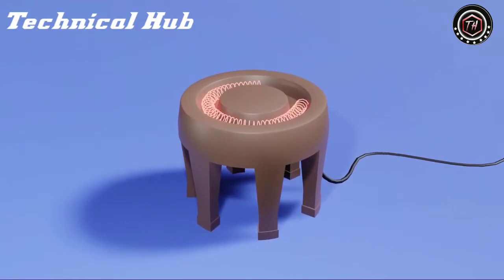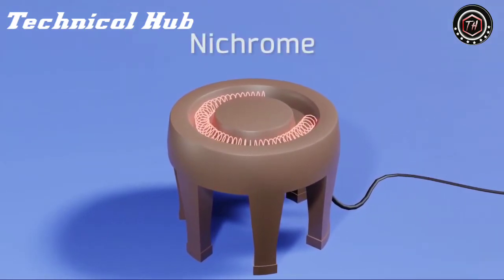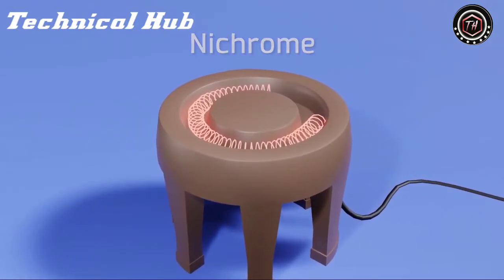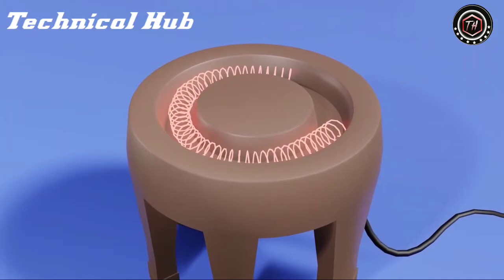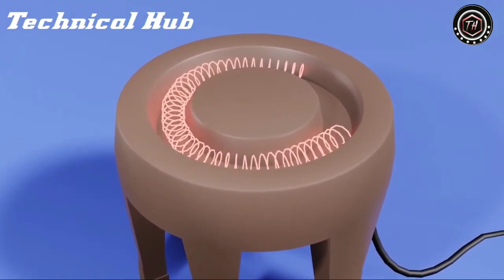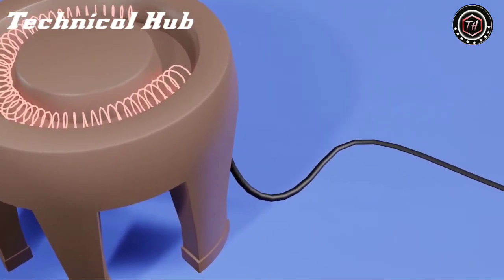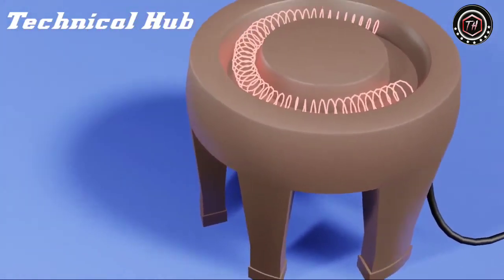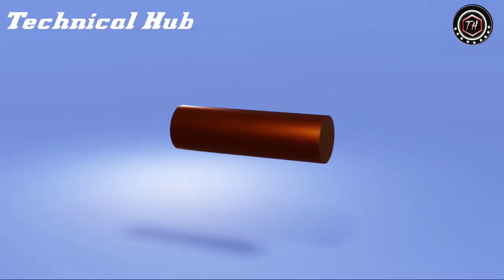That is why for such cases, alloys such as nichrome are usually used, which, in the first place, has a melting point of 1400 degrees Celsius, and also has a high coefficient of resistance. This last characteristic is precisely the reason why only that section is heated and not the cable that we plugged in. Going back to the main topic, now that we know how to get a quantity of ohms to our